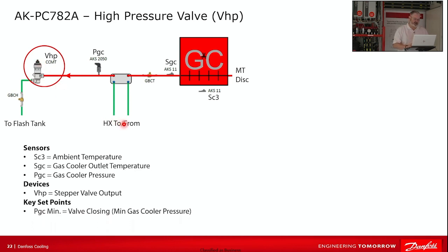What I said is kind of interesting is the set points. You just give it a minimum gas cooler pressure and you define a maximum. Think of that as wintertime, low ambient. I don't want it to get below some certain amount. So let's say our flash tank, we've set it at 520. We don't want the head pressure getting anywhere near that, so we'll set that at like 650, 700 pounds for our minimum. And then we set a maximum for a 110 degree day. We don't want it to get above 1,450 pounds before we relieve pressure to gain control of the gas cooler.